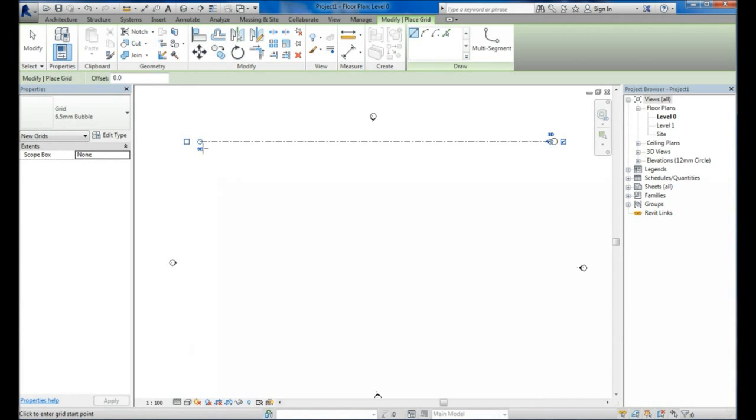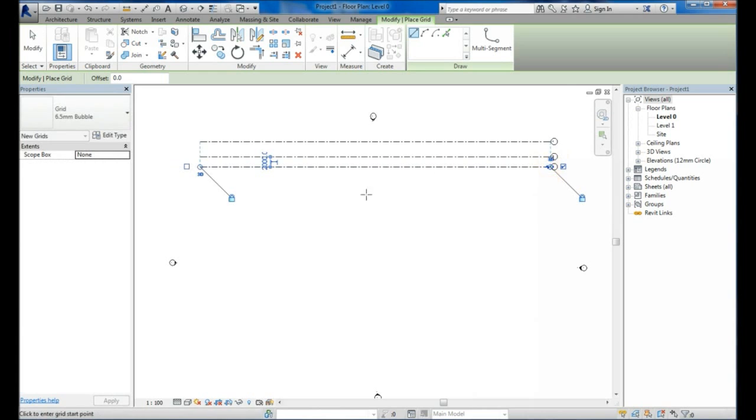I'm going to do a 3 meter grid this way. So if I look for 3 meters, just nudge it onto it. If you remember, you can actually type this in if you wanted to. That's 3 meters. Move it to the other side. I'm going to do a corridor of 2 meters next. So if I click there, 2 meters, take it to the other side, and I should do another 3 meter distance. Click from there, move it to this side.